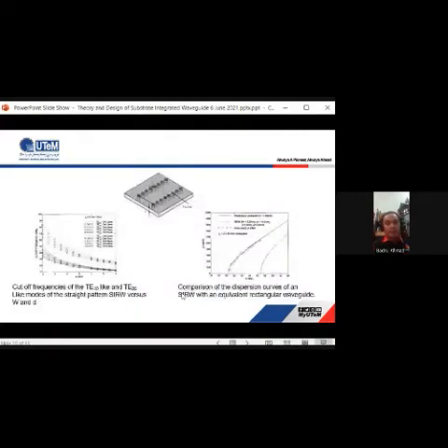This is the study that was done by previous researchers, whereby the dispersion properties of the substrate integrated waveguide were rigorously obtained using the BI-RME method, derived from Floquet's theorem. From this analysis, we can see that SIW basically has the same guided-wave characteristics as the conventional rectangular waveguide.